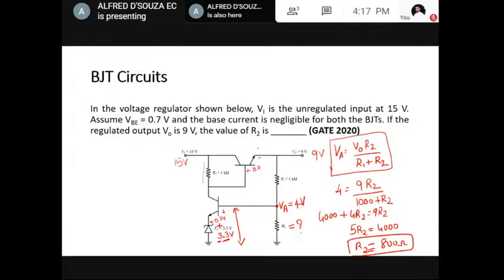Don't worry about all these components and how they work. It is used to maintain against changes in the voltage, and it provides the compensating current. Those circuit elements are for compensating, that's it. The voltage across the zener diode plus 0.7 will give you the voltage at this point. Then it is a simple voltage division rule. Instead of this transistor, one can also use an op amp, something like this.